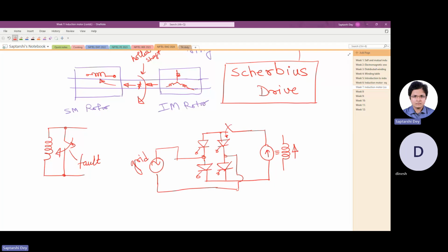This is why I told you to turn on the thyristor control first, then close the switch. Otherwise, if you close the switch first, it may damage some of the thyristors because of the high voltage. Or maybe for security, you can keep the thyristor control circuit on throughout. That will not cause any harm. So when there is a fault, you simply close the breaker, and energy will be sent back to the grid. But again, I am saying all this from a theoretical point of view. Feasibility and all needs to be checked.